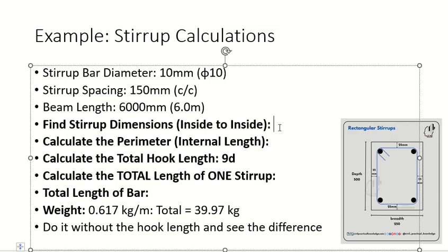So concrete in this section can be weaker because you did not leave enough cover. So leaving this cover is important to make the concrete strong, and to make sure that if there is a crack, anything which goes into the crack, moisture, water, sand, whatever, will not go directly to the steel. So we need to have some gap so that the bond is strong between steel and concrete, and the concrete does not become weak at the edges, okay, clear.